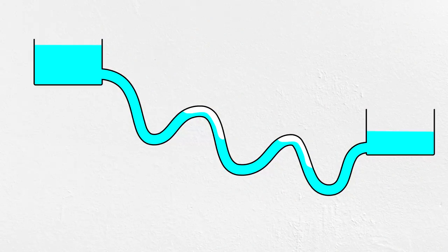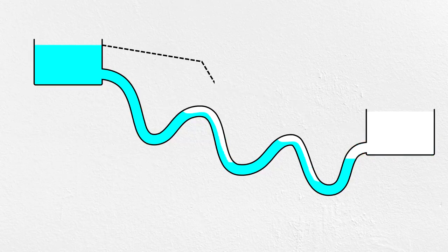Every undulation in a pipe with a trapped bubble of air is going to rob the fluid of this energy. And if the hydraulic grade line drops below the outlet of the pipe, you won't get any flow at all. That's the definition of airlock, also called vapor lock.